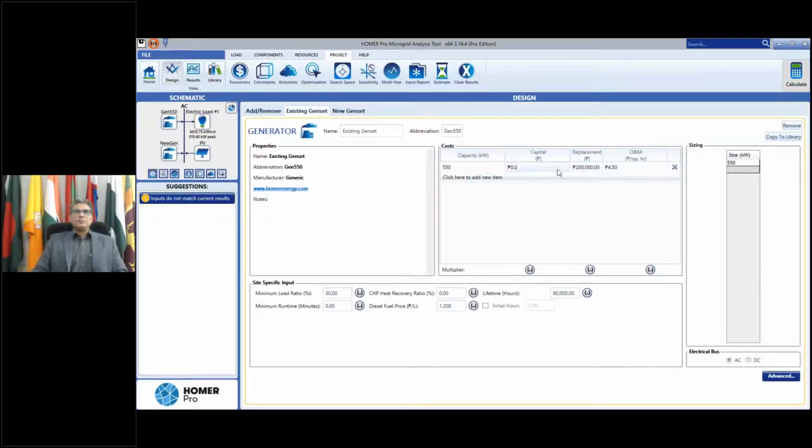But the numbers are the same. It did not convert the values into Philippine currency with the exchange rate. It just changed the symbols. That's why when you start modeling, you should start setting the currency right according to your requirement, and maybe have an Excel file of all the components priced on a single currency, converted to that single currency. So from US dollars or euro, you can have it in Philippine peso or Indian rupee or Indonesian rupee.